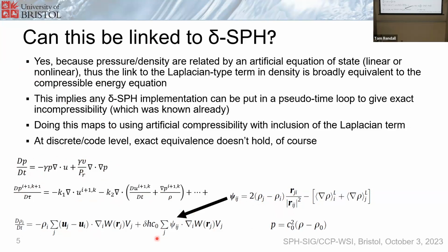Obviously at an exact numerical level, these methods are different due to the way they're implemented and the scalings that are chosen by the different authors, but there's quite a lot of overlap in terms of their origins, I would say. The only thing you really need to keep in mind is that with the delta variant, you're looking at density, so it's weakly compressible, and it's written in terms of density, and there's a particular equation of state that you use. But if you were to exchange density and pressure, these results become importantly comparable, I would say. So there's overlap there, essentially, between artificial compressibility and delta.